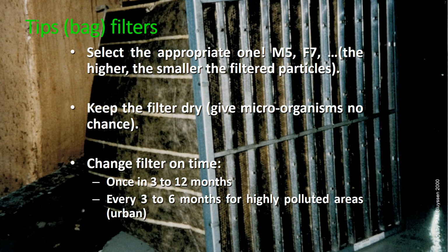Next to keeping the filters dry, it is important to change the filter on time, preferably when the system is off. Depending on the situation, traffic and other sources, this is once every 3 to 12 months, but in general every 6 months for highly polluted areas and once per year for low polluting areas.